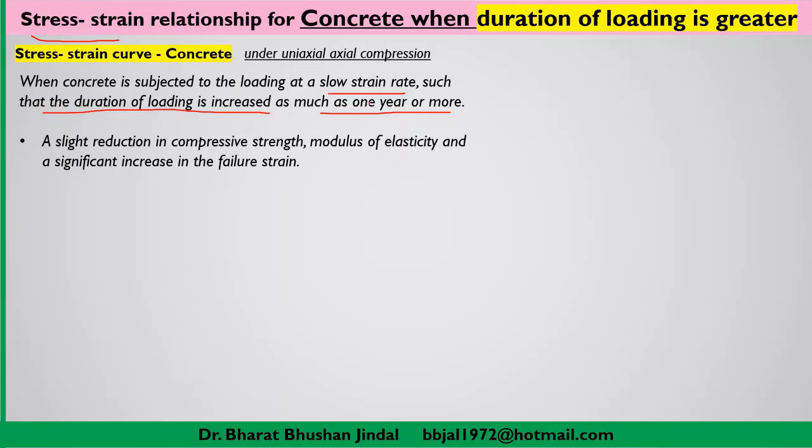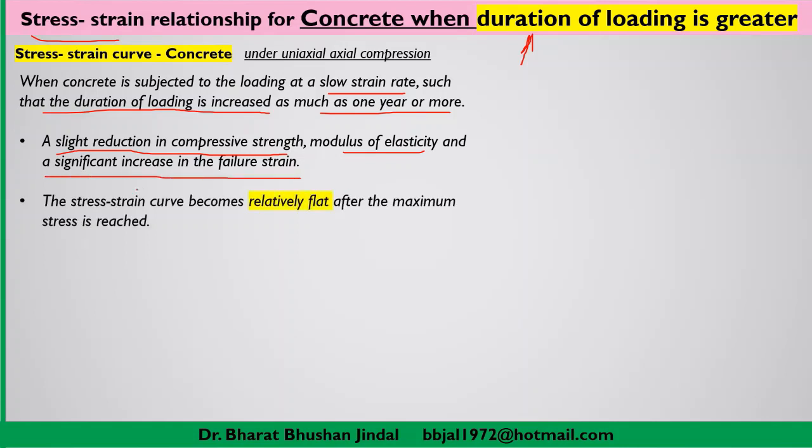So when you draw the stress-strain curve, when the load is acting for a larger time period, you will find a slight reduction in the compressive strength, modulus of elasticity, and a significant increase in the failure strain. Stress strain curve becomes relatively flat after the maximum stress is reached.